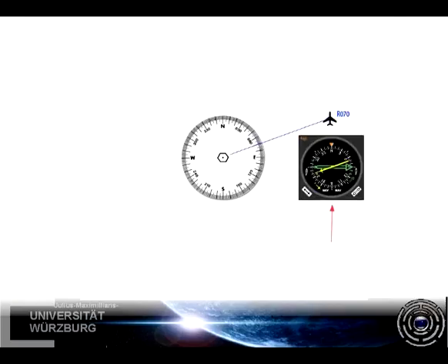This is an RMI. It is part of a compass system and shows our current heading, which in our case is spot on north. The thick green arrow is the second navigation system, which is currently offline. In this case, the needles always point to the right wingtip. Our VOR receiver is tied to the yellow pointer. As you can see, the bottom of the needle points to 070, the radial, and thus the pointer is showing the magnetic bearing to the VOR station, the opposite bearing, in our case 250.